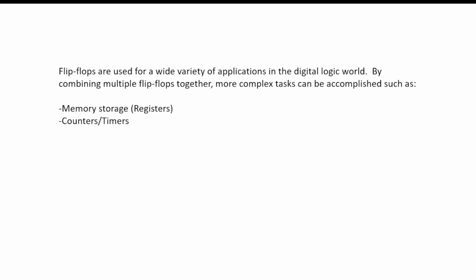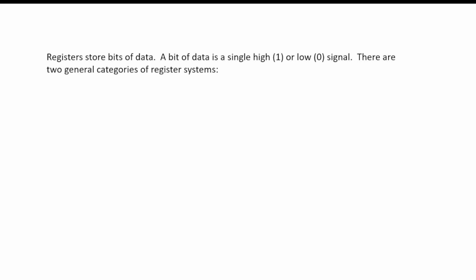Now, flip-flops are used for a wide variety of applications in the digital logic world. By combining multiple flip-flops together, more complex tasks can be accomplished, such as memory storage, which is known as a register, and counters and timers. Let's look at memory storage first. Registers store bits of data. A bit of data is a single high or a low zero signal.